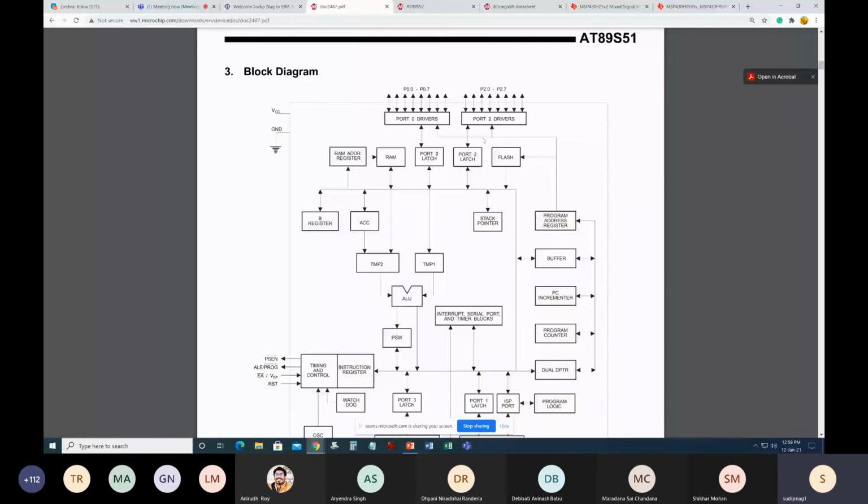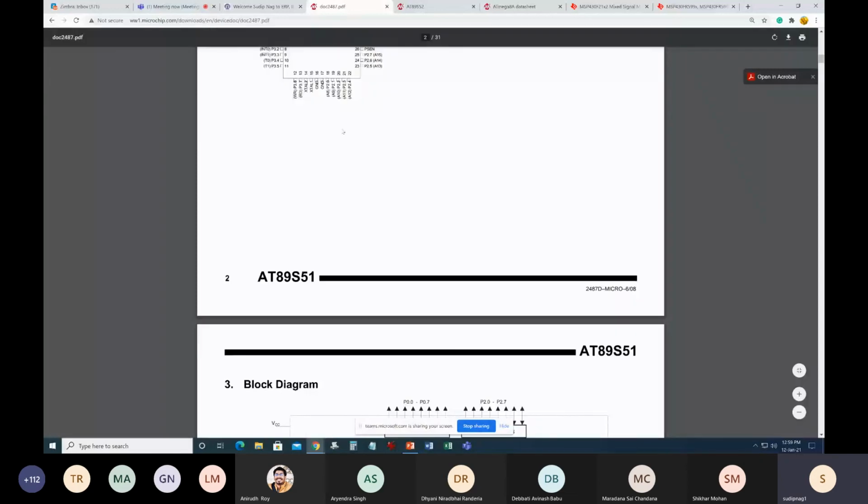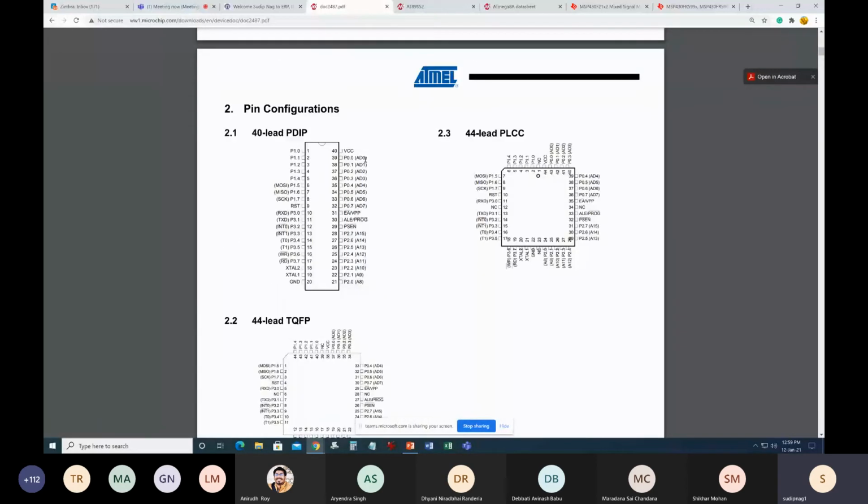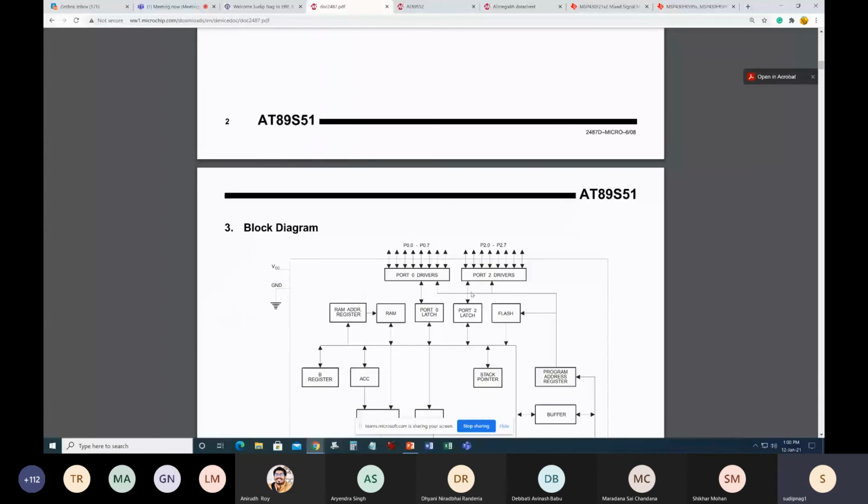How I'm telling you, because based on the logic. You have a 16-bit address line, A15 to A8 and then A7 to A0. So there are 16 address lines. However, you just have 8 data lines, D7 to D0. Okay, so for the address part, the program counter is a 16-bit register.